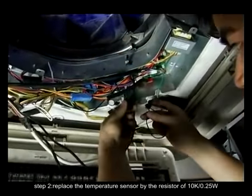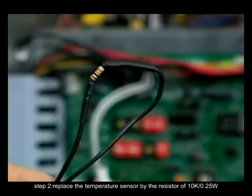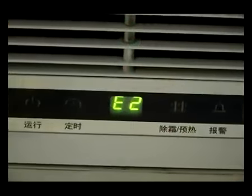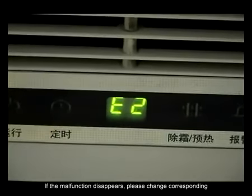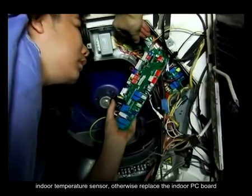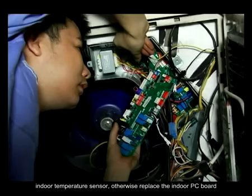Step 2. Replace the temperature sensor by the 10K per 0.25 watts. Then check if the malfunction disappears or not. If the malfunction disappears, please change corresponding indoor temperature sensor. Otherwise, replace the indoor PC board.